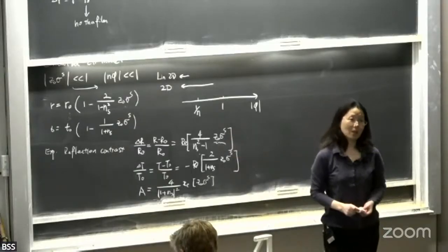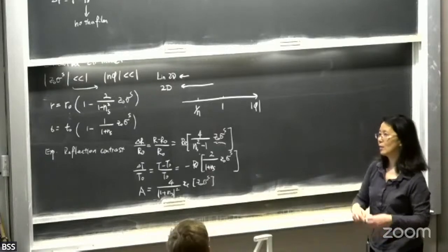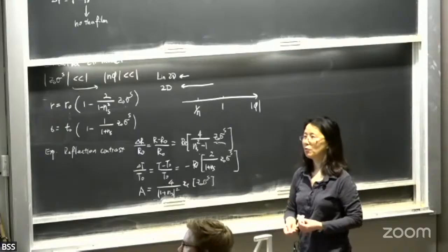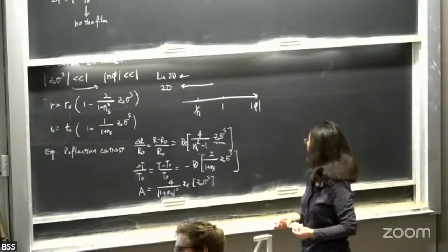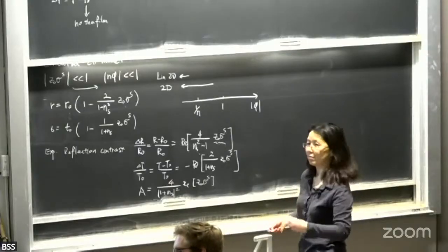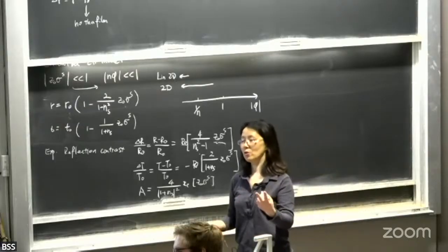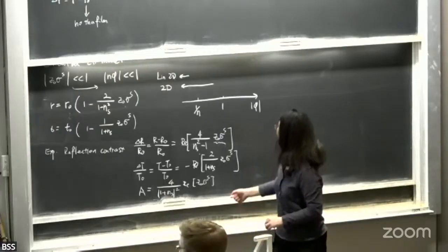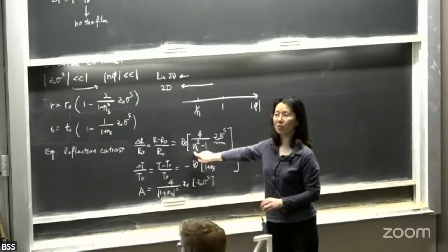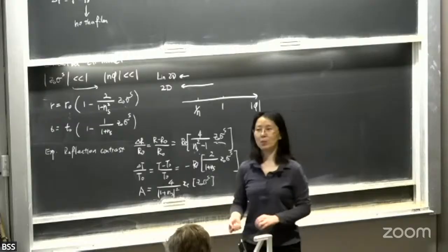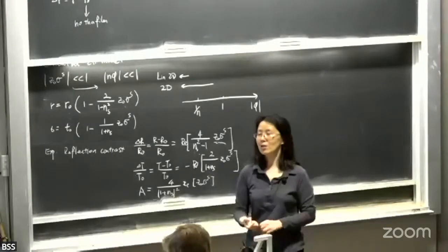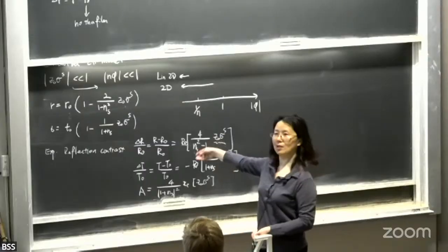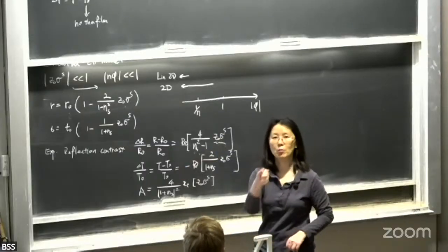And often this is enough, but in order to get the full complex information of the sheet conductivity, you may do, for example, 2 measurements, one with a transparent substrate when this NS is real, and then move to a different substrate when NS is complex, and combining those 2 measurements, you can get information of a real part and imaginary part.